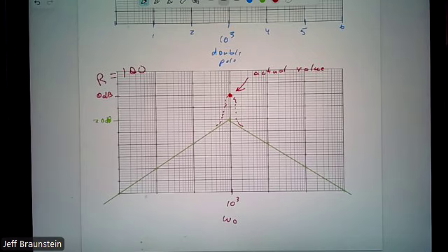And so strongly underdamped, narrow bandpass filters, voltage across the resistor, but strongly underdamped. Went from that wide passband, then to the whatever it was, 10 to 10.5, to something very narrow located at 10. And we can underdamp more, move this down more, this gets narrower and narrower. In some ways, it's like old tuners work.